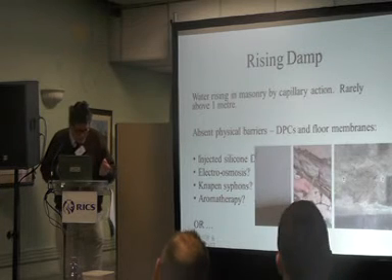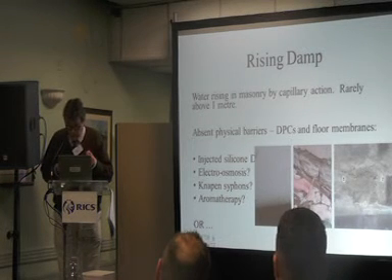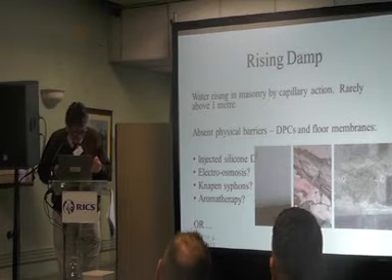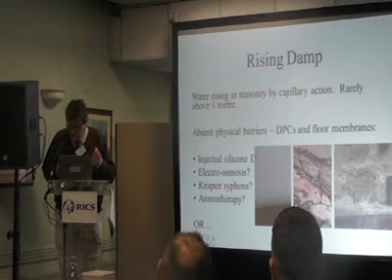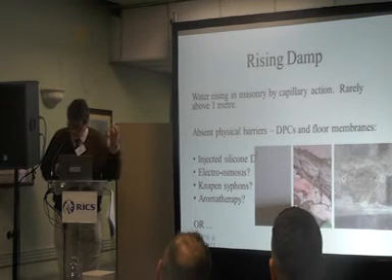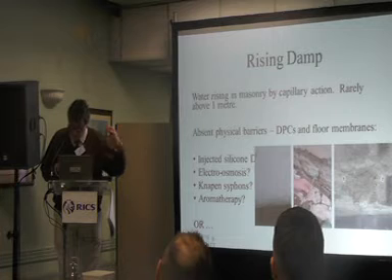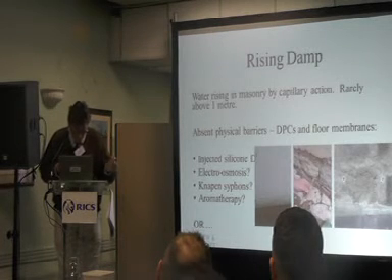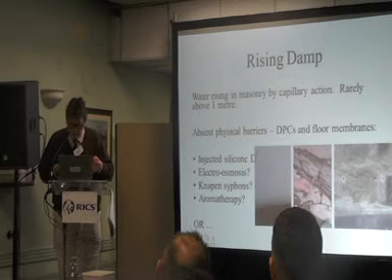Now, I do want to just break at this point and talk about measuring moisture. The definitive test is an oven test. You take material, send it off to a laboratory where it's weighed, oven dried, weighed again. That is definitive, but it takes too long. It's not practical. Conductivity.